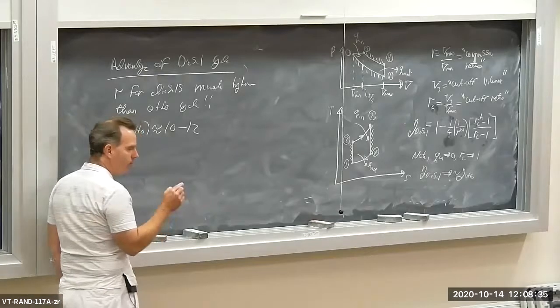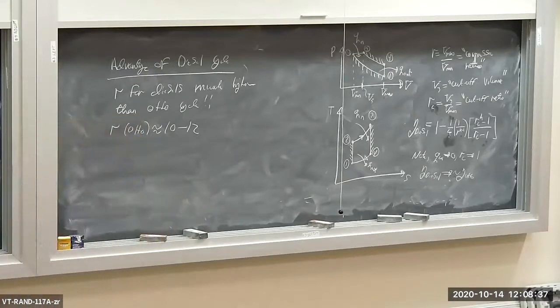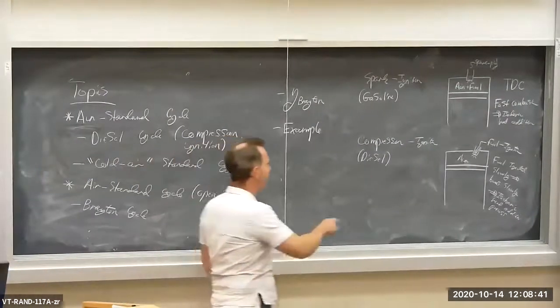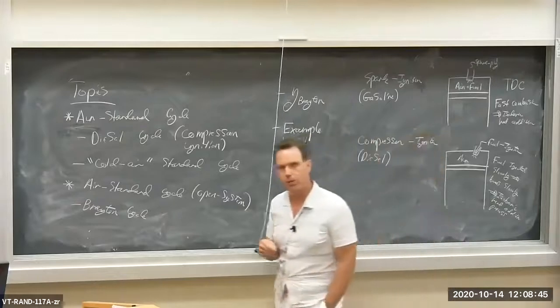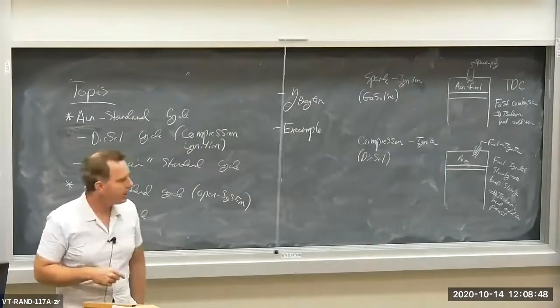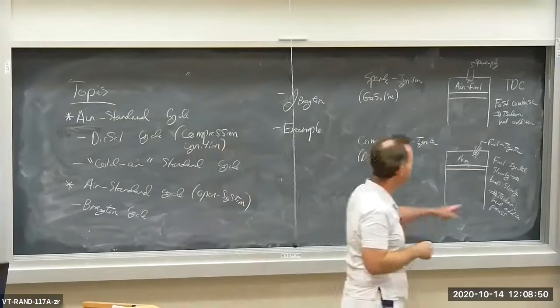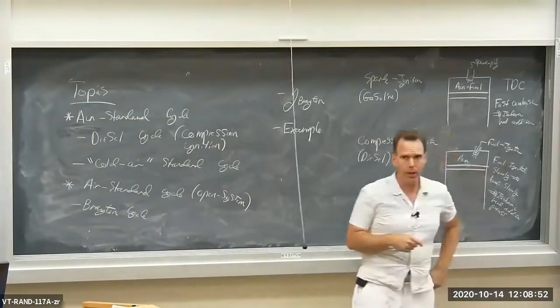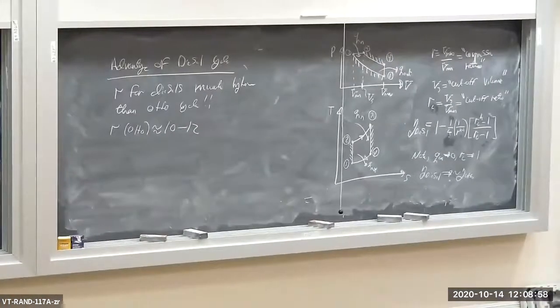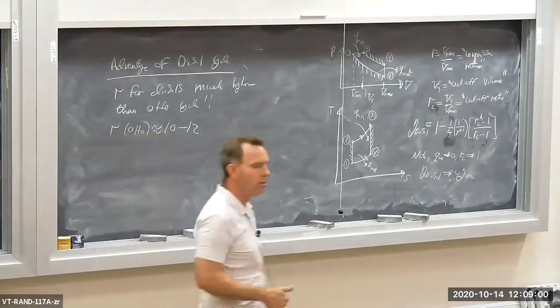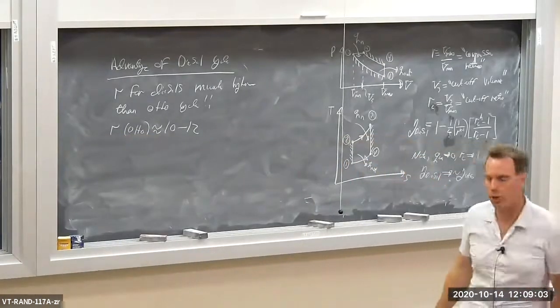On the other hand, for diesels, where you're compressing air, not air-fuel, you don't have this inherent problem with knocking. The rate of heat release is controlled by the injection rate for the fuel, and we have pretty good control over that. So knocking is not really a technical problem for diesel development, so we can crank up the compression ratio quite high.